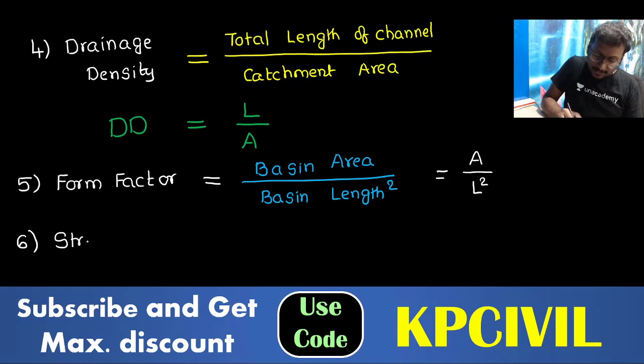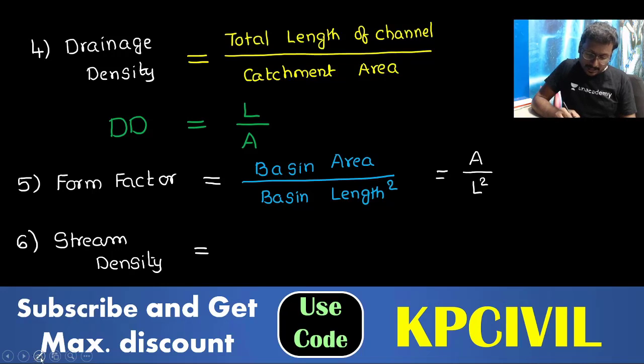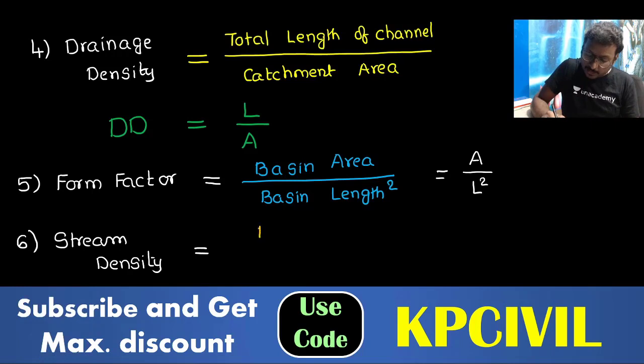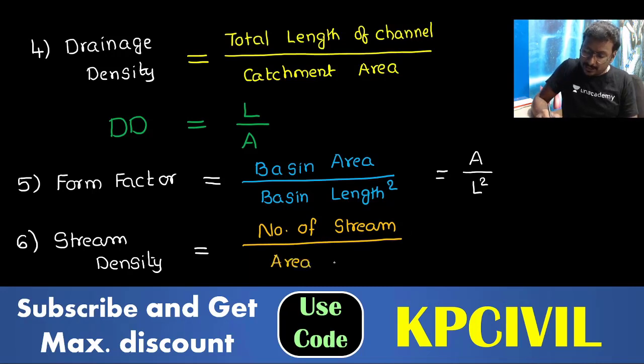Stream density. What is stream density? Stream density, SD. We can write down stream density as SD. Again, it is the ratio of the number of streams available in the catchment, the number of streams available in the basin, to the area of the basin. So stream density is the ratio of number of streams to area of basin, N by A.